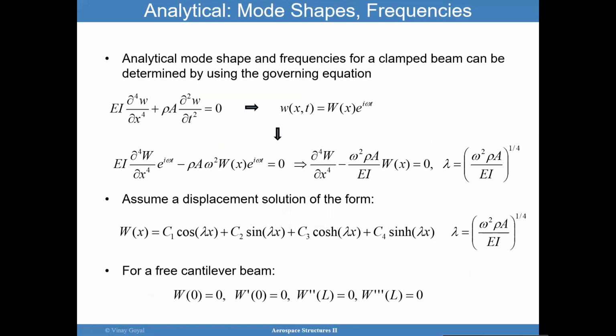Why would I examine and remind you a little bit about the basics of some of the vibration problems that you could encounter? So let's say we want to solve this free vibration problem of a beam. And again, every time you're working on frequency extraction procedures, we're talking about solving the free vibration problem. So here's your mass times acceleration term. This is the beam deflection equation that you may have seen.